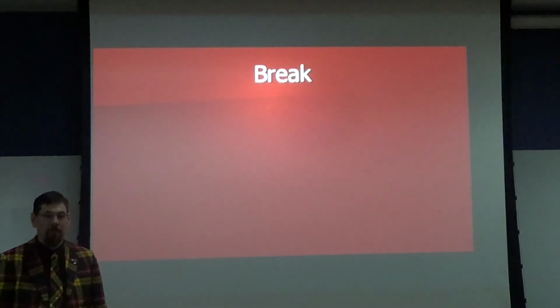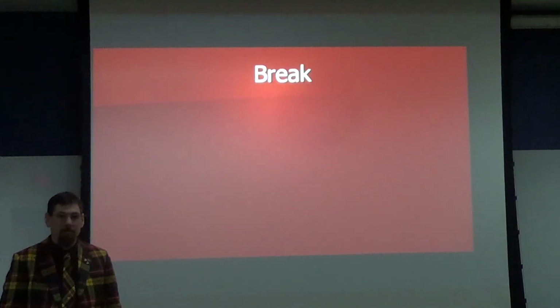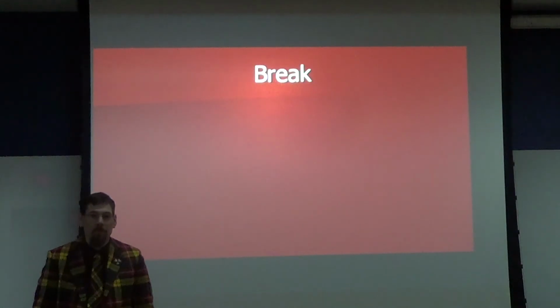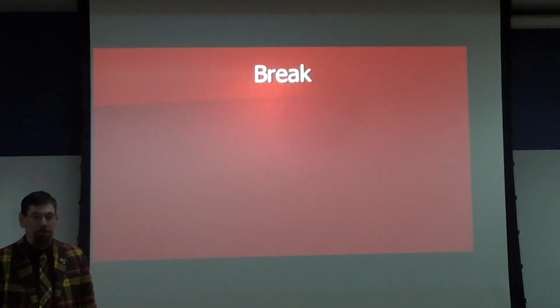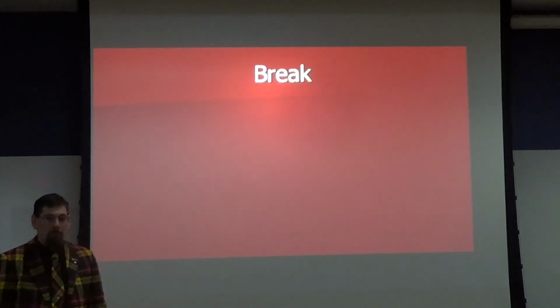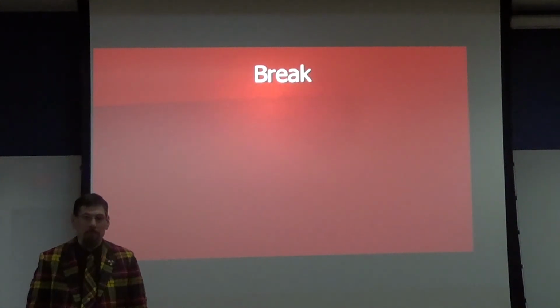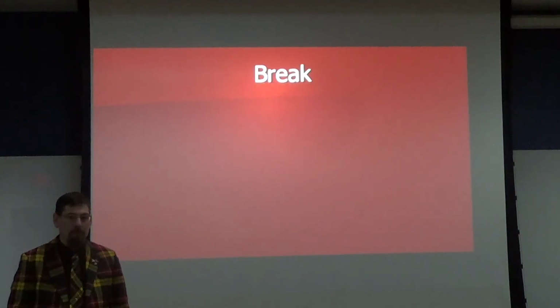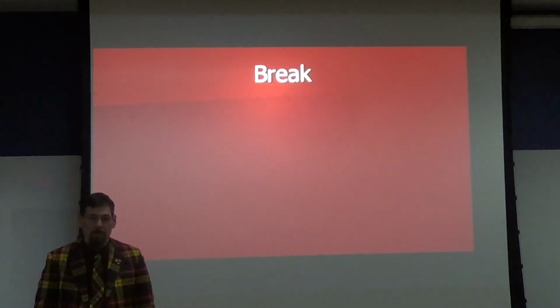When you forge weld it, the slag oozes to the surface and protects it from oxidation, so you don't have to put separate flux on it. That's why in the olden days a blacksmith could solid state weld two pieces together without having to put flux or worry about oxides on the surface so much. So it's a pretty cool material, even though it's not made anymore.